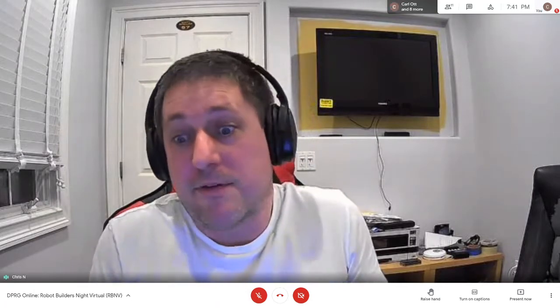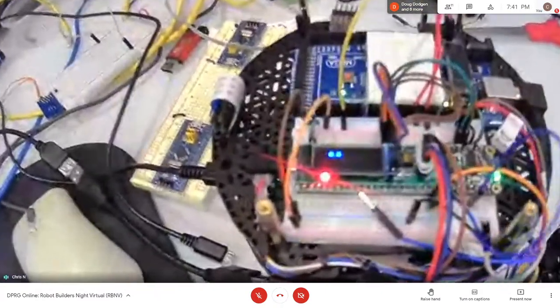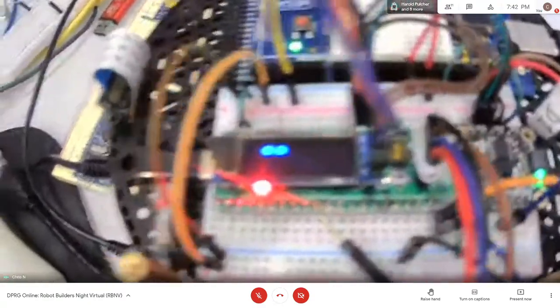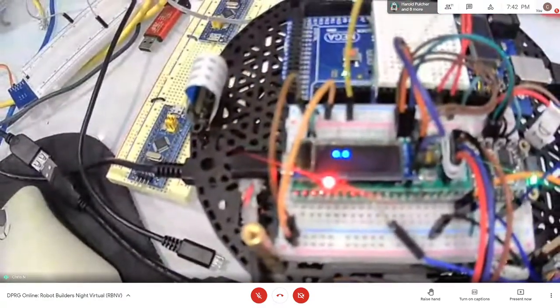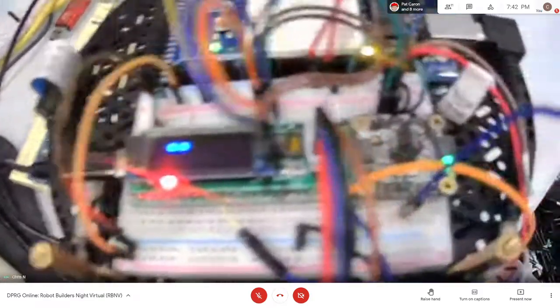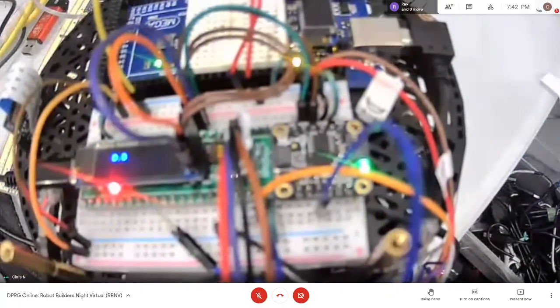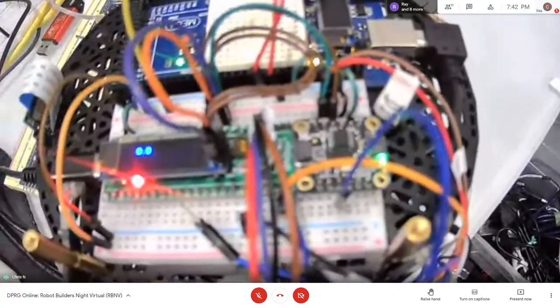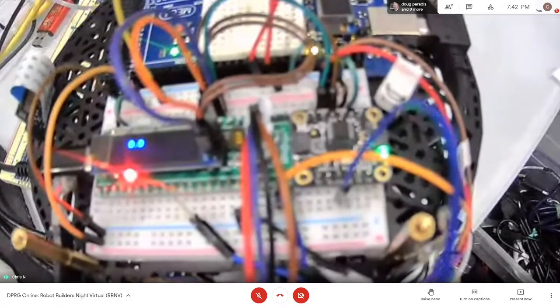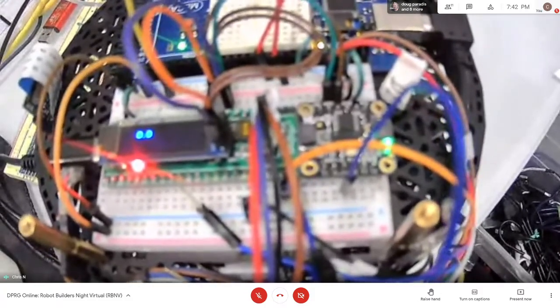If I remove the BNO from the equation, I have a little OLED on the same bus, and first I suspected the STM32 as the culprit. But I have the OLED here on the same bus, and then over here I've got the BNO, the little breakout board, on the same bus. The moment I just hold the BNO in reset, everything's fine.